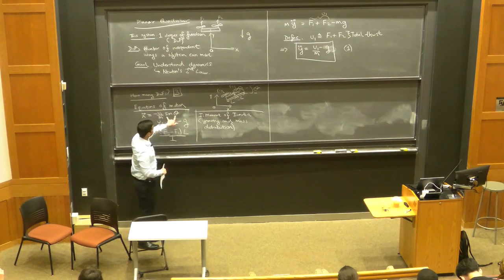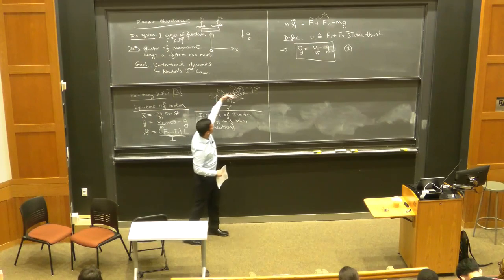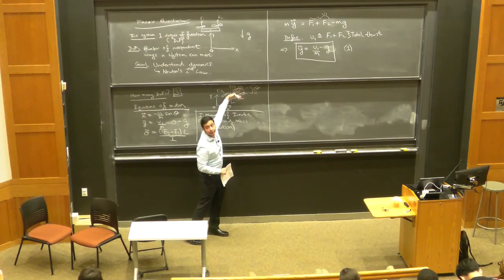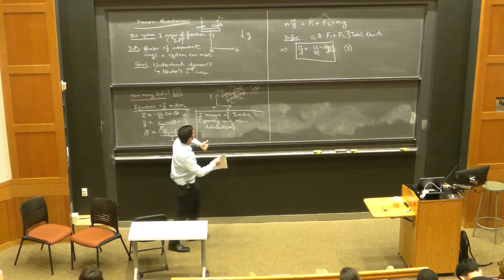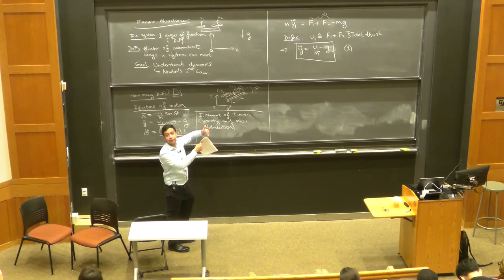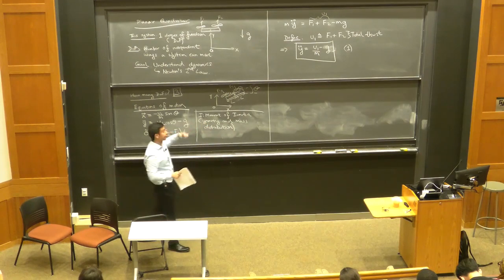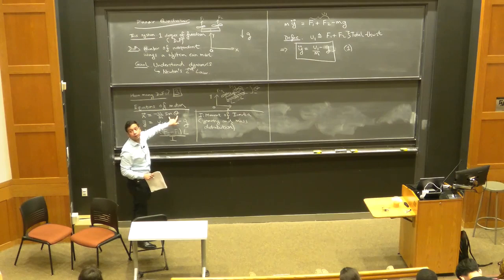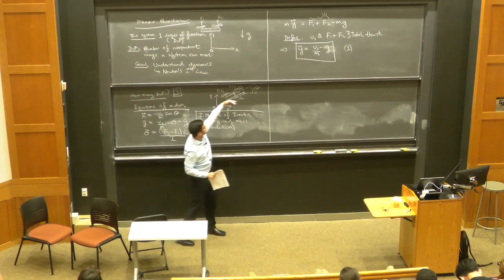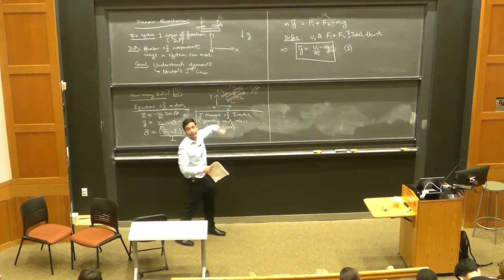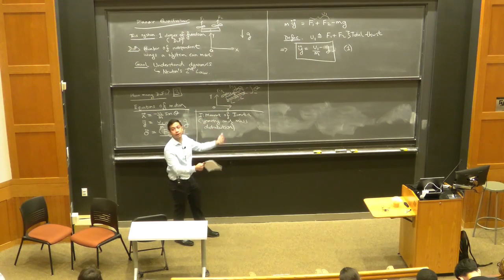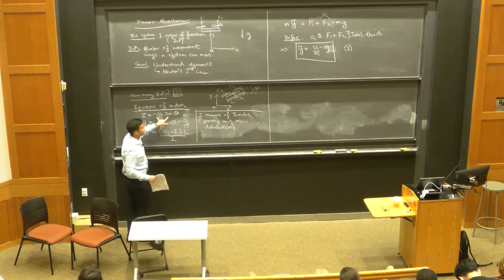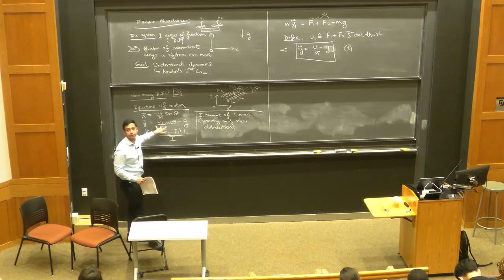So okay, yeah, we can check that as well. So let's say theta is 0. So in that case, the drone is completely horizontal. In that case, the thrust force is completely vertical. And so there's no x component, right? So sine of 0 would be 0, and so that checks out. And if theta is slightly positive, then the thrust force in the x direction is slightly higher, but in the negative direction. So I think this checks out, and the same in the y direction.